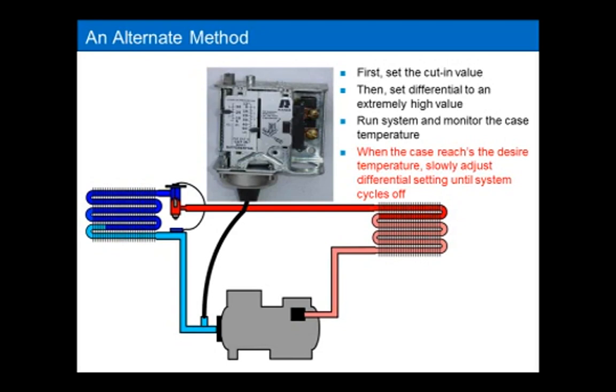You don't necessarily have to remove everything, but remove enough so that it doesn't take that long for the case to drop temperature. If you remove enough product from the case, it's not going to take you that long to drop. But if you have this box that is loaded up with a lot of product, this method will take you a while to achieve. It's a great method, but there is a handicap of waiting. So I hope that will help you on some jobs. It really has helped me on some situations where I couldn't get that calculated cut-in value right.